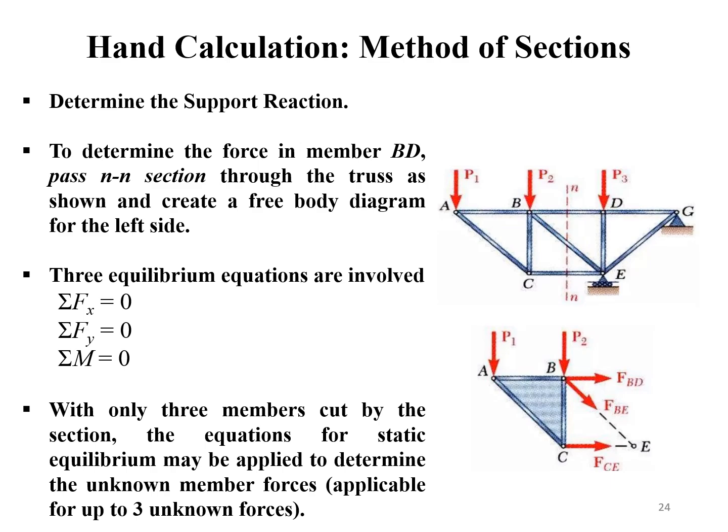Now we have covered the method of joints. Let's look at the other method we can use to solve trusses, which is the method of sections. The first step is the same as the method of joints. We draw a free body diagram and use the equilibrium equations to solve the reaction forces. Next, we make an imaginary cut through the members of interest in our truss, and we can draw the internal forces in the cut members.